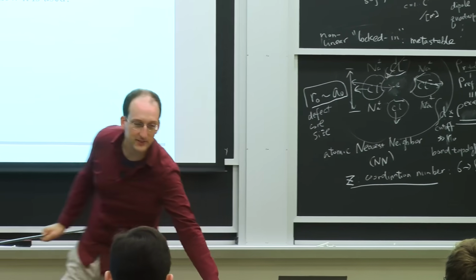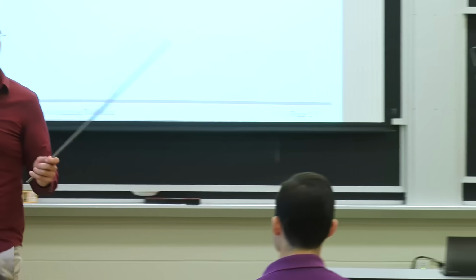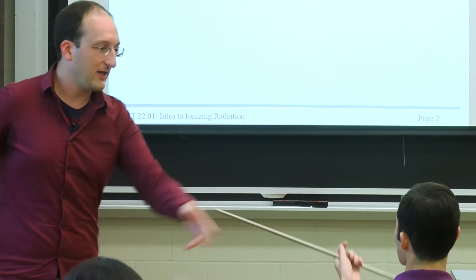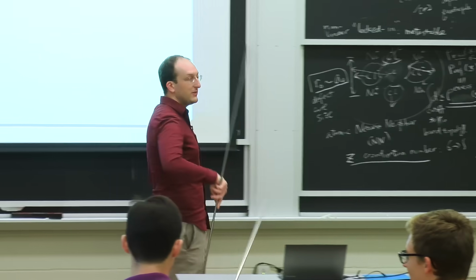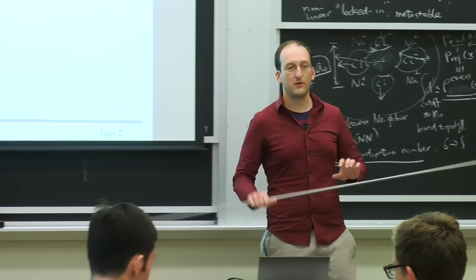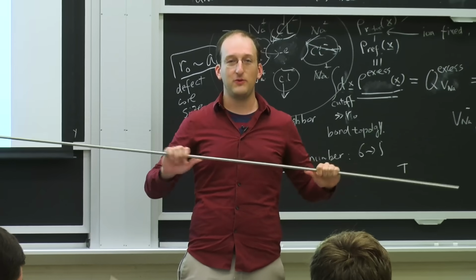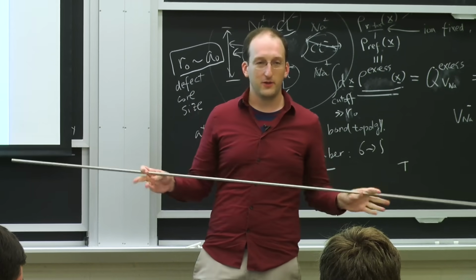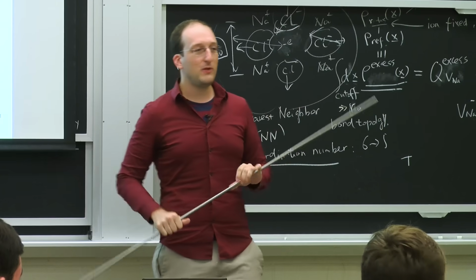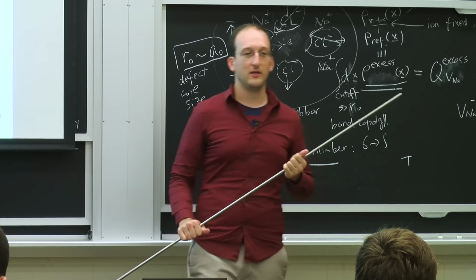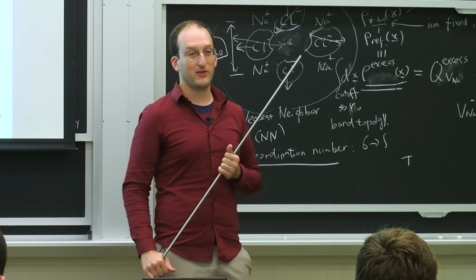And I wanted you guys to see and feel and try and bend what Zircaloy actually is like. That's a piece, the same diameter and dimensions and stuff that you would see in a nuclear reactor. So give it a slight bend. If you try really hard, you can bend it. But notice how light it is. Notice how strong it is. It's about midway in density between stainless steel and aluminum, but it's a hell of a lot stronger than aluminum.